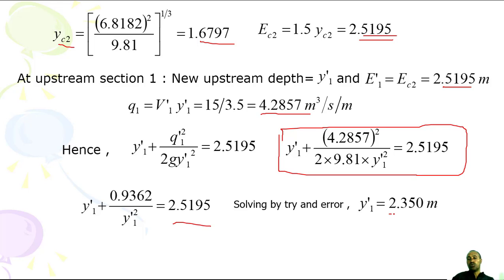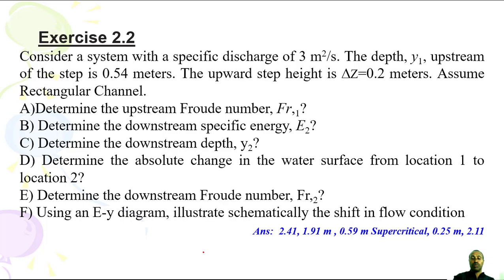So when the width of the channel is going to be reduced more, then you are increasing the depth of water in the upstream section. Let us see the pictorial presentation. I think this is an exercise you can try. Just answers are given here.